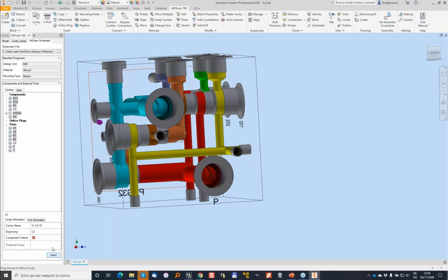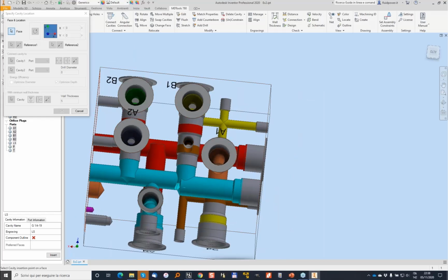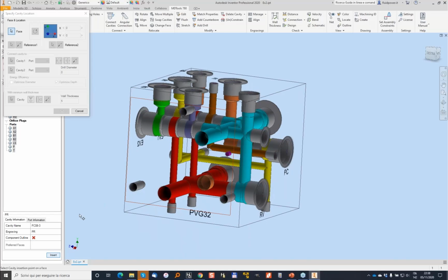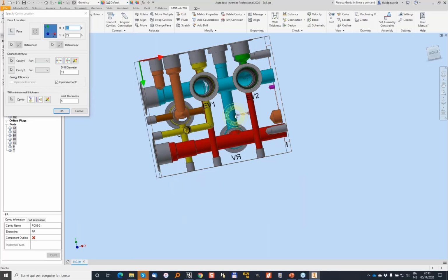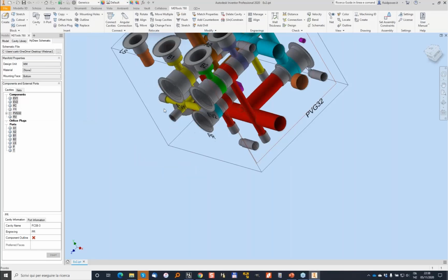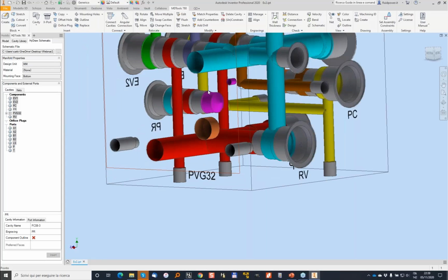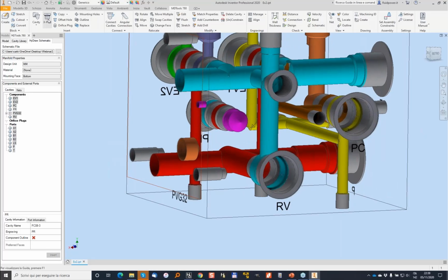Let me put the LS somewhere, and let's say that it is going to be here. Customer wants it to be there, and we need also the relief valve for the pilot. The pressure reducing valve, let's say that the pressure reducing is here. So now we want to make some inclined drills, and maybe with some strange inclination, dual inclination.